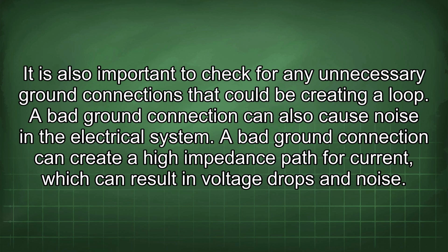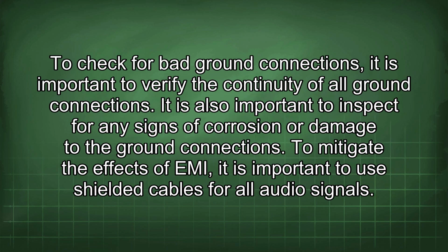A bad ground connection can also cause noise in the electrical system. A bad ground connection can create a high impedance path for current, which can result in voltage drops and noise. To check for bad ground connections, it is important to verify the continuity of all ground connections. It is also important to inspect for any signs of corrosion or damage to the ground connections.